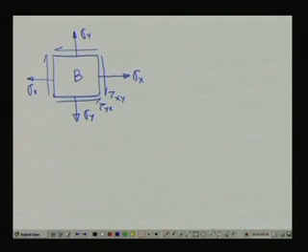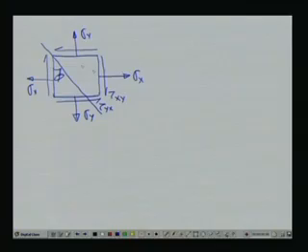One important situation comes into the picture: if you have this type of combination of sigma y and tau xy, the shear stresses and the normal stresses, then we have to find out the combined effect of sigma and tau. Not only that, we also have to find out what the stress is at that particular point at any other orientation.